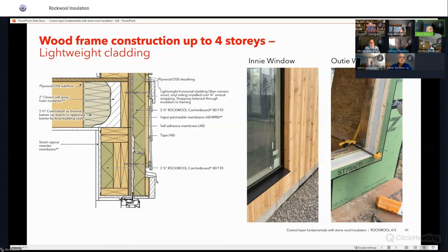Then you'll have your exterior extension jamb, which you can see here with this knotty cedar. And then your finishes will go on the outside of that. Or like in this picture, you can pull that window out by bucking that system out. This builder decided to do an insulated buck where, in this case, he did plywood, 2x4, insulation, and then another layer of 2x4, and then connected that all.